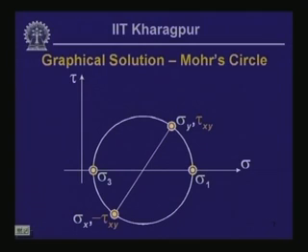So, if you consider the 2 points on a Mohr circle representing the state of stress at a point within a 2-dimensional element, then the point that is on the right end is going to be called the major principal stress, and you should notice that on this particular plane the shear stress is 0, and the one on the leftmost extremity of the Mohr circle represents a state of stress that is called the minor principal stress, and the shear stress on this point is also 0.